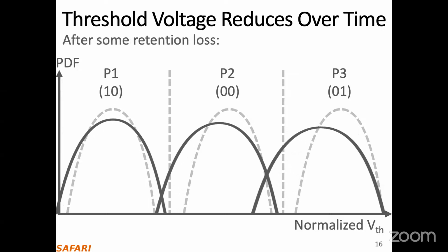So when your flash chip is working, after some time you will see that these distributions are shifted and they are also widening. They don't just nicely shift to a lower threshold voltage. That's also challenging, but if they were only shifted and didn't conflict, you could still fix your errors.